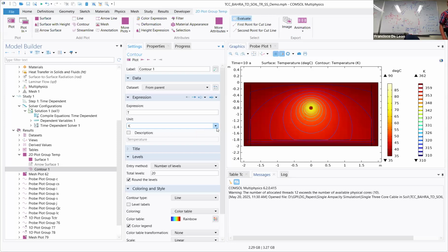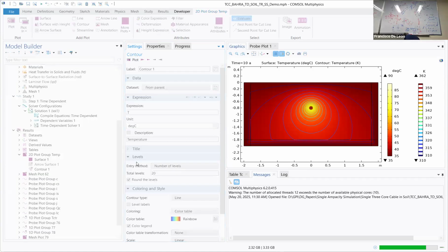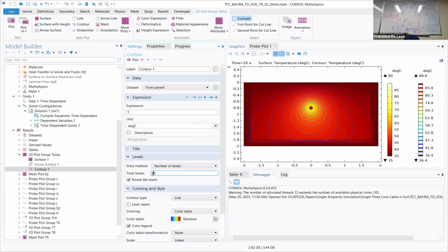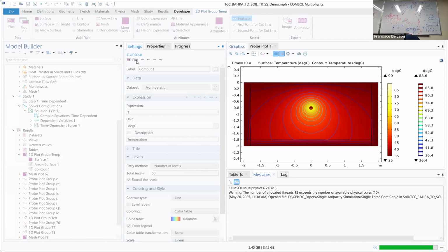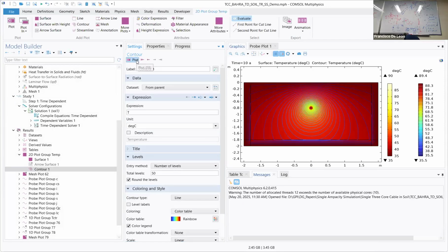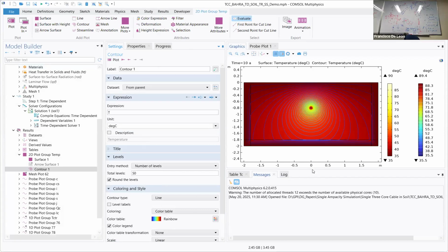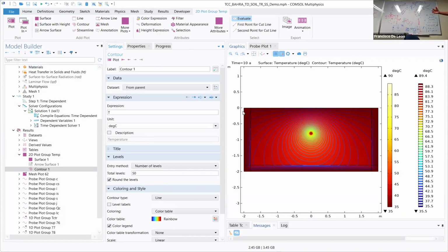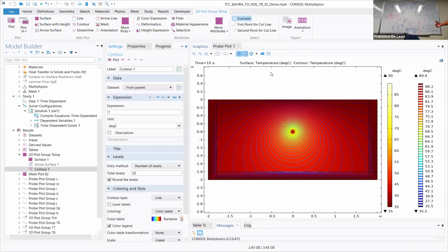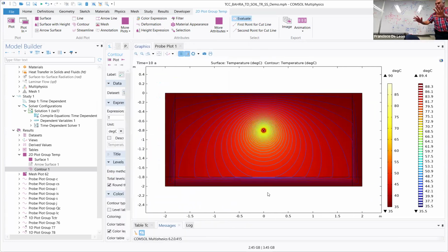There you go. This is really how the heat is dissipated. As you can see, going up, the gradients are closer. From here to here, the heat in the end will dissipate this way, but it diffuses down to the ground. If you remember the explanation of diffusion, you come with a bucket, throw it in the carpet, and it expands like this, diffuses, but it has a maximum reach. It doesn't go to infinity. It goes to infinity in an exponential way, e to the minus something, but you know that after 5 tau, 5 time constants, it doesn't matter.